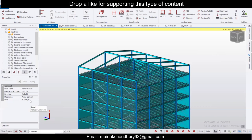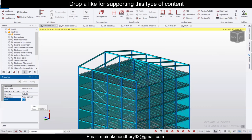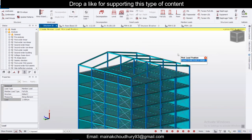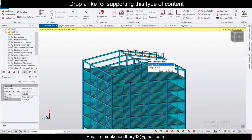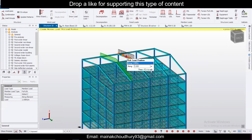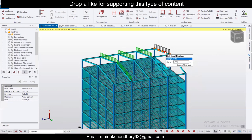Similarly for the imposed loads also we'll do something similar. So for the imposed load, let's take an imposed load of 0.2 kilonewton per meter square, so it will be 2 at the middle and 1 at the ends. So you can calculate as per the material used, and as per the code you can calculate. So no problem in that.